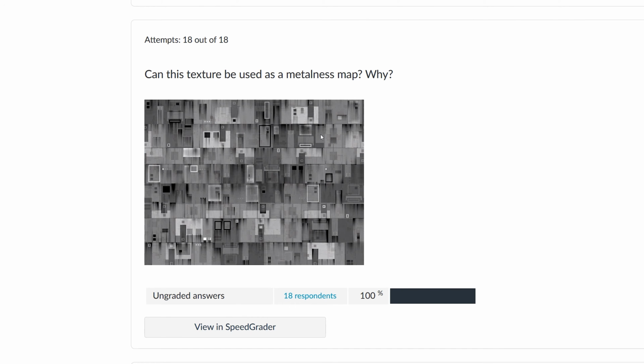By the way, I see this all the time. If you grab some kind of PBR texture or you're exporting something from Substance Painter or Designer, and you get a pitch black metalness map, meaning that nothing on your object is metal, please don't load that in, because you're wasting resources. Maya has to load that and do something with it. If it's just pitch black, leave the value as 0.